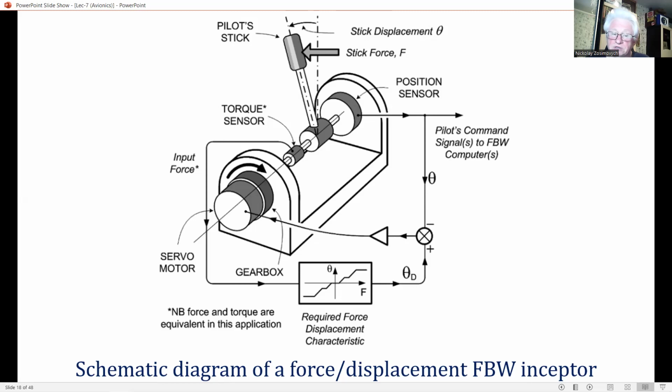Brushless DC servo motors are chosen because of their excellent torque characteristics and reliability. Very effective damping can be provided by the inherent electromechanical damping in the DC servo motor, amplified by the feedback within the servo amplifier. Consider what happens when the pilot exerts a gentle pressure on the stick to displace it from the normal central position.